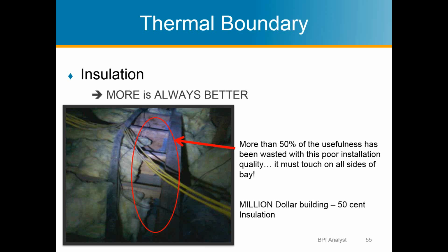If you have any questions, please feel free to type them into the question box. I do have a few questions that I can handle while Scott is out. One of them is, what is the best insulation to use for walls when there is existing drywall? So this would likely be in an existing building. Typically, this would probably be a blown-in cellulose.